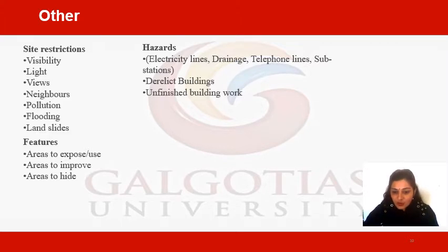The result of this analytic process is a summary, usually a graphical sketch, which sets relevant environmental information in relation with the morphology of the site in terms of parcel, topography, and built environment. A number of graphic tools have been developed by designers purposely for site analysis, and an example of a traditional climate-related site analysis tool is the sun chart.